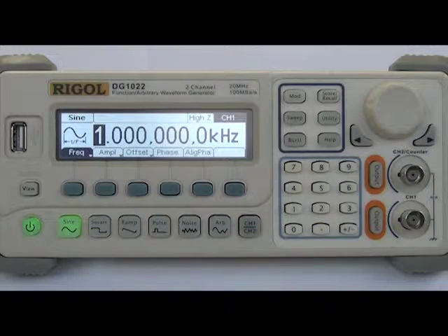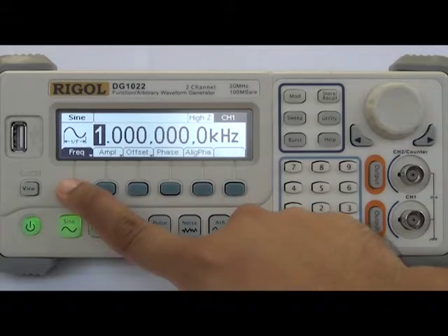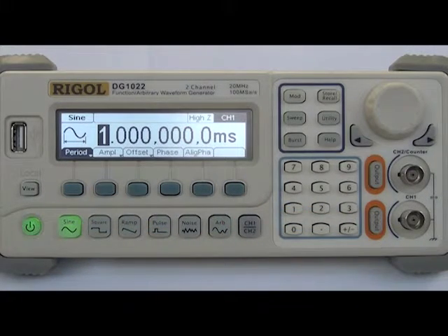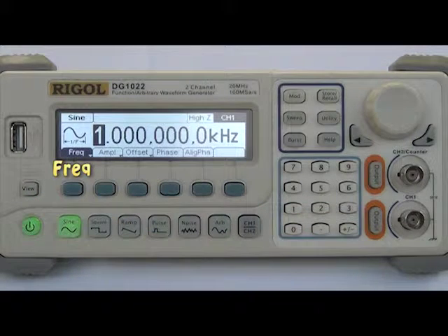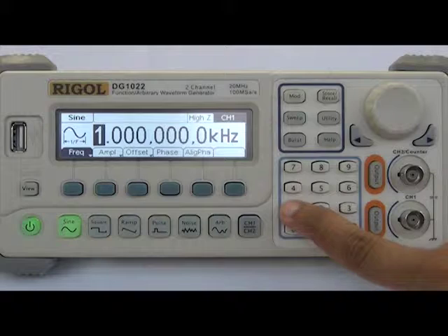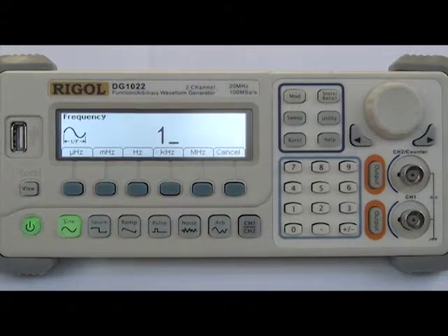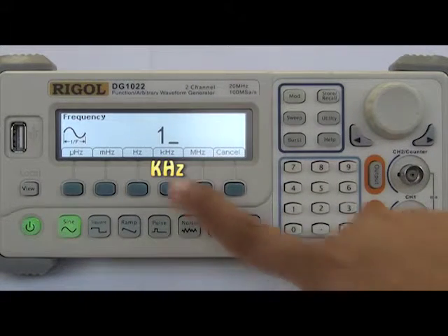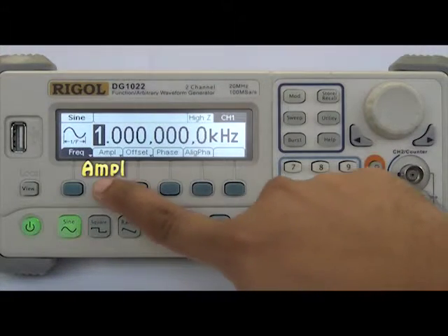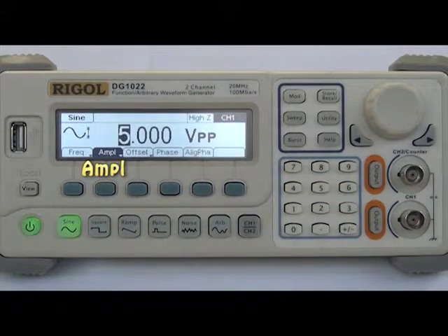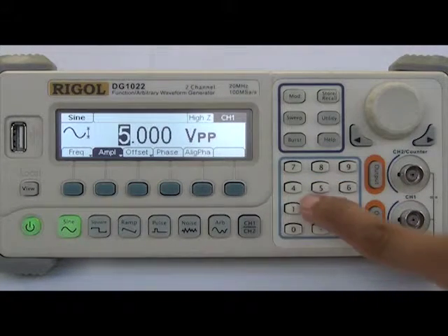In case you happen to see a period at the start, press the button again to change it back to the frequency mode. Enter the value 1 on the keypad and press kilohertz option. Next, to set up the amplitude, press the amplitude tab and enter the value 2 on